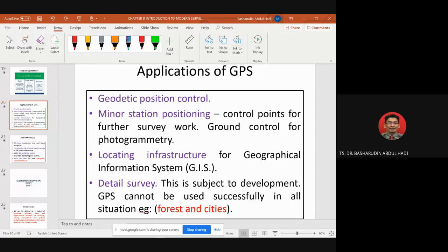Before you put that marker in the arrow position or triangle position, you put a static GPS and take the reading for at least 30 minutes for X, Y, and Z. And then you record X, Y, Z, the data about your clock times, the coordinates, and the dates. Okay?